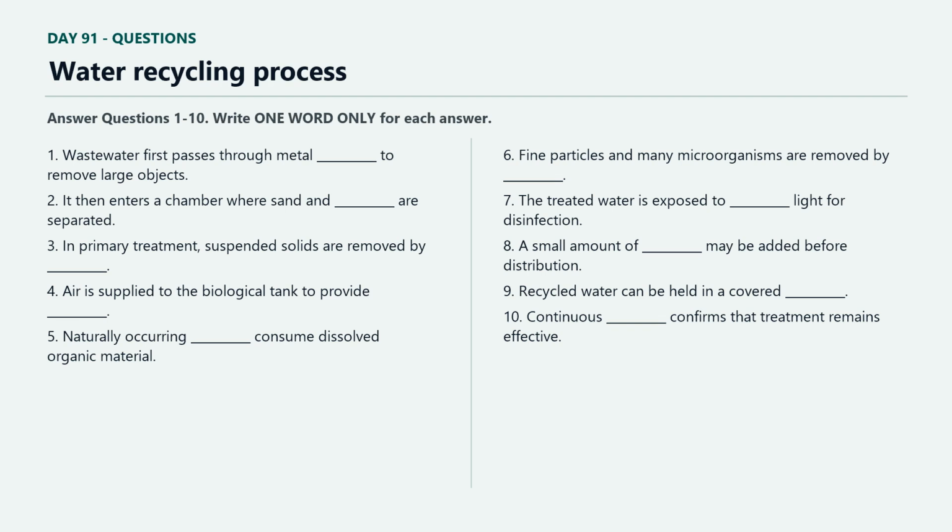Some recycling systems add reverse osmosis after this stage. Reverse osmosis uses a much tighter barrier and high pressure to remove dissolved salts and many small chemical compounds. It produces a concentrated reject stream that must be managed responsibly. Because reverse osmosis consumes substantial energy, it is selected when the required quality justifies that cost.